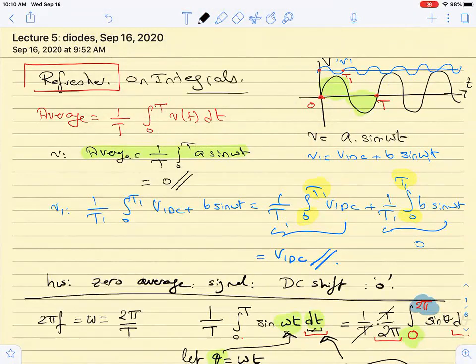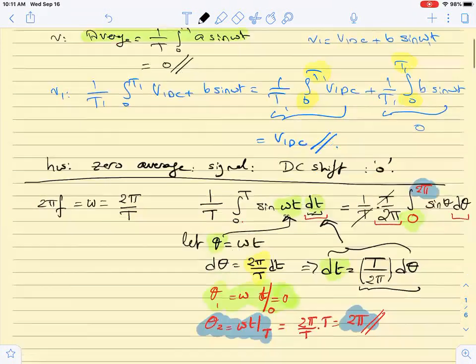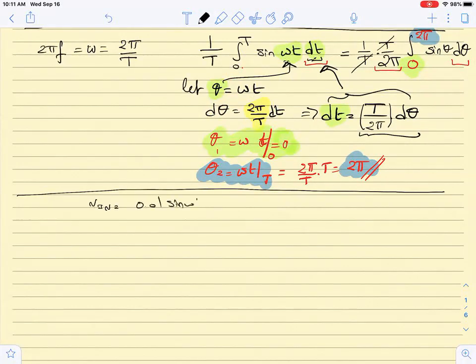Yes, please, can you repeat? When do we say that Pin is equal to 0, and suppose PDC equals P out plus P lost? Okay, so you are asking me now about the power, right? Typically, if my input signal Vin is, let us say, 0.01 sin omega t, the VDC is around 9 volts, times current, which is 1 milliamp, this is 9 milliwatts.